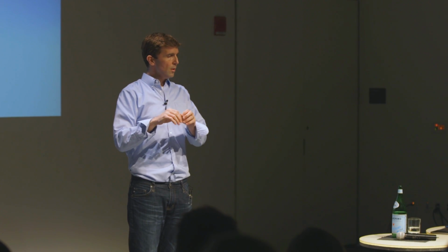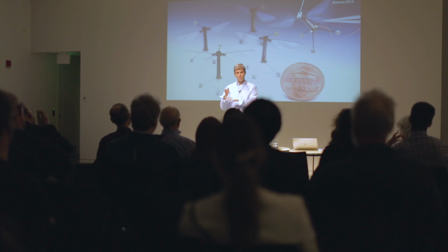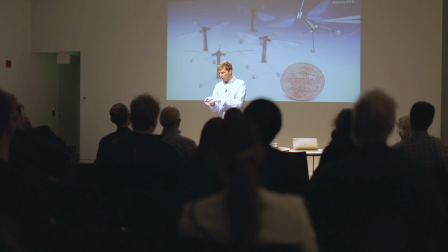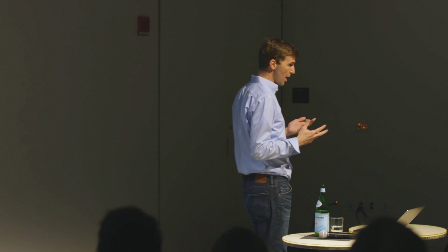So anyways, we actually use a lot of passive modes in these devices. And one of the passive modes is this rotation. So we actuate this motion and allow this to be passive and just tune. This is mediated by a little flexure hinge, a little fold at the base of the wing that you probably can't really see here. By tuning the inertia of the wing, the axis of rotation of the wing, and the stiffness of this flexure, we can get this quasi-static rotation mode tuned to the appropriate phase relative to flapping to generate optimal lift. And it turns out after we did this, we looked back at the biological literature, and there's a lot of evidence that flies do the exact same thing.